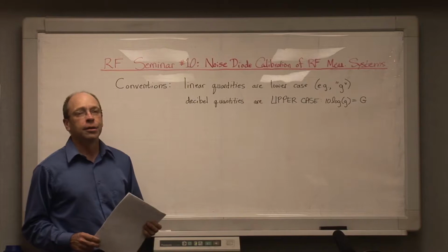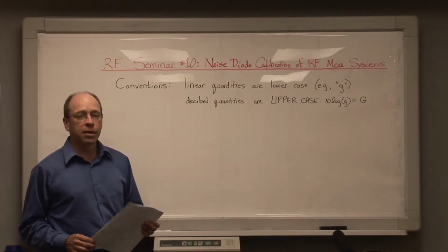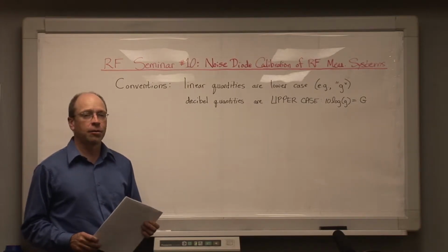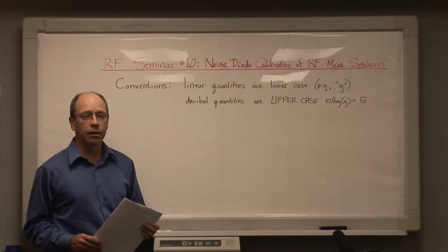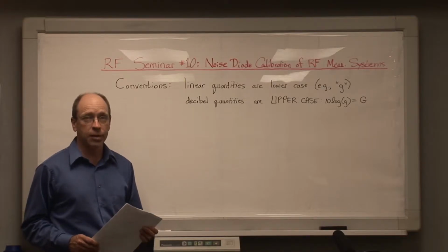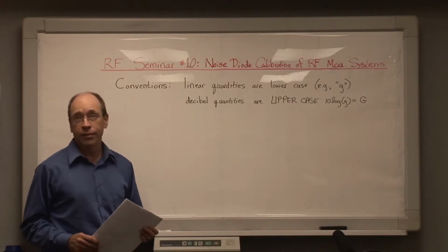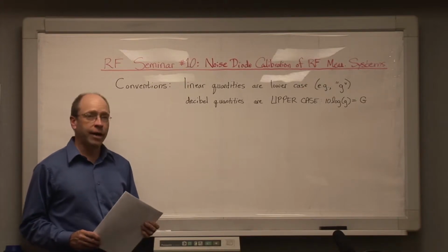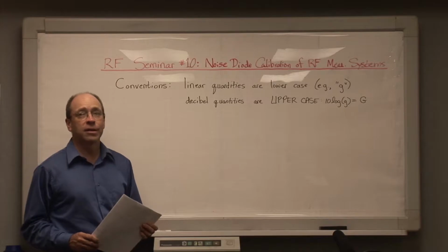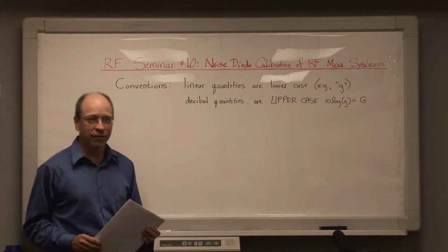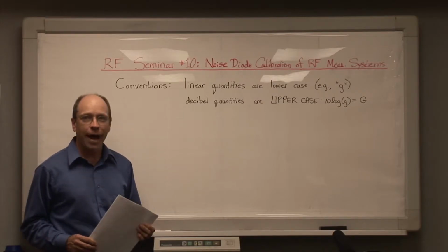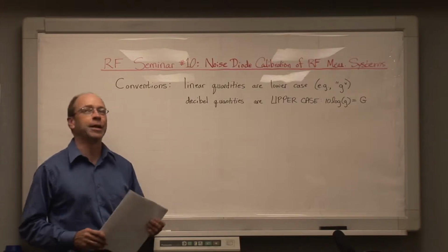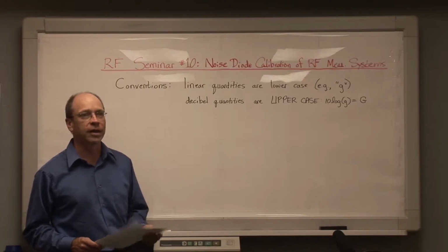We'll also describe the use of a couple of different low noise amplifiers and show why sometimes a low noise amplifier can be put into a measurement system and not do any good for the measurement system, could even degrade the measurement system. Other times why we need to put in a low noise amplifier, but we also need to add some attenuation between the output of the LNA and the rest of the measurement system to actually optimize noise figure and dynamic range, which maybe seems or could seem a little bit counterintuitive.